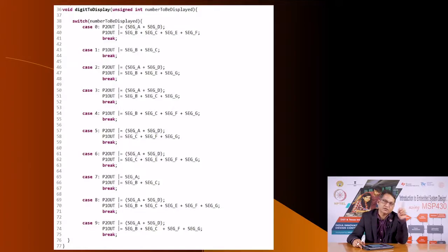The count is stored in a memory location of the type volatile, so that the interrupt subroutine, especially the timer interrupt, will be able to pick the count, and based on the value that has to be currently displayed, from that count it will be able to display exactly that count on that digit, and it will happen smoothly.